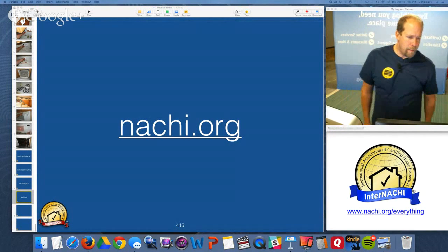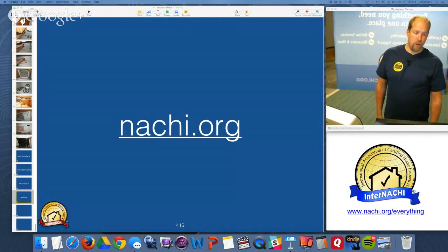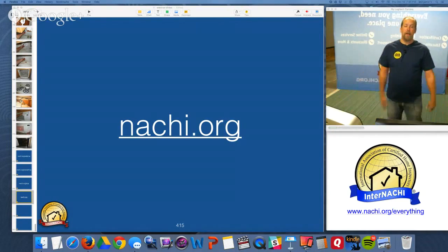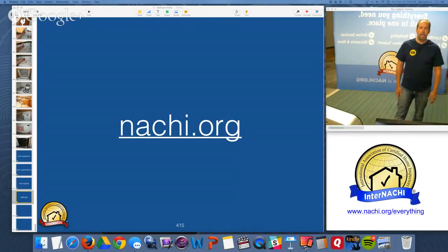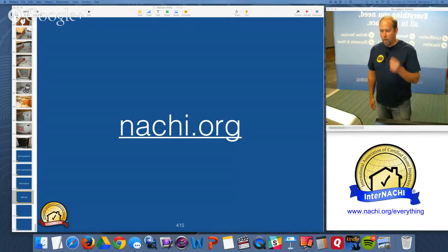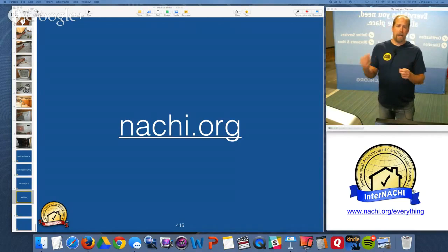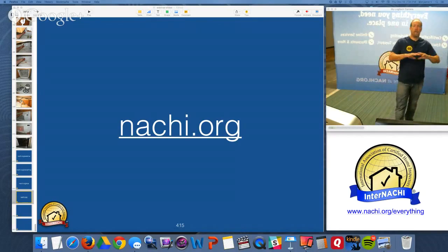Greg again. Ben, do you test receptacles for AFCI and GFCI breakers from within the home using your tester? Yes, I do. But I'm really careful because nowadays, I learned my lesson. I turned off some bedroom receptacles and there was a computer plugged in and that wasn't good. So I make sure that I'm more careful with AFCIs than I am with GFCIs. GFCIs, I test them. I don't even ask for permission.